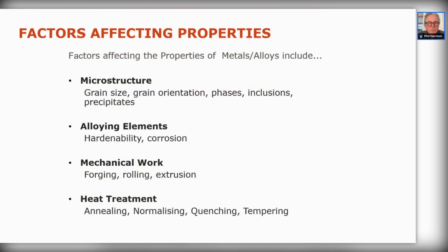For example, when I mentioned machinability earlier, we have in steels something called pearlite. It's a mixture of two other phases, which is ferrite, very soft, and iron carbide, which is very hard. By extended heat treatment at just below 700, about 650-ish, the long plates of iron carbide form these balls or round up a bit, and these give you the chip breaks that improve the machinability of the material. So again, by heat treatment to modify the phases in there, we are modifying the properties. We'll go a little bit more on that when we get to heat treatment.